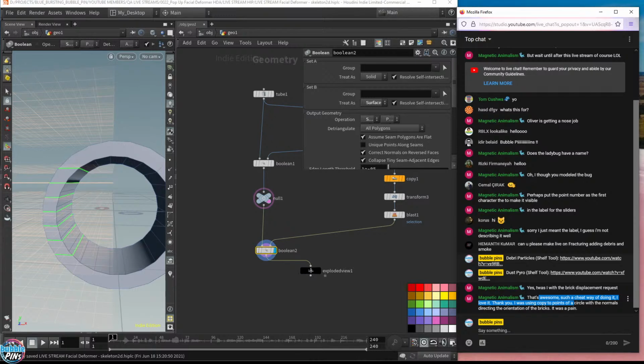This way, this cheaper way of doing it, you can actually slice it differently. Like you can position the grids in a different area. You can have one grid higher, or just skip a grid. Just do what I do, delete one of the grids and then slice it. So this way you can guarantee that each layer of the brick is touching the bottom layer. So they're just easily doing it like that.